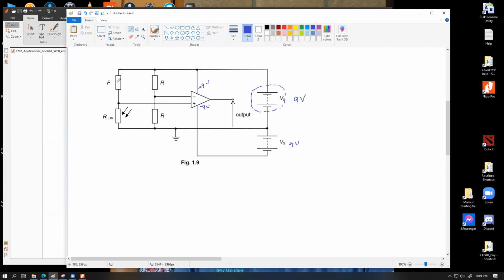Here you can see two resistors in vertical. There is a potential divider circuit. And the midpoint of these two potential divider points is drawn and connected to the op amp inputs. So here's the deal. This top 9 volt supply is going to be responsible for providing this, which means this voltage is going to be divided over here, and then we're going to do some comparison.